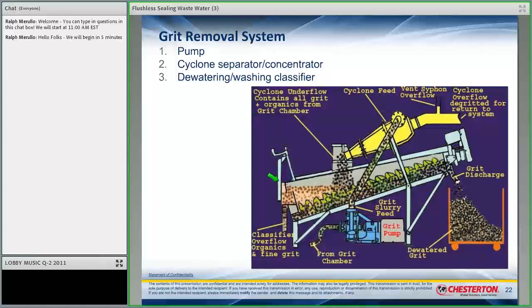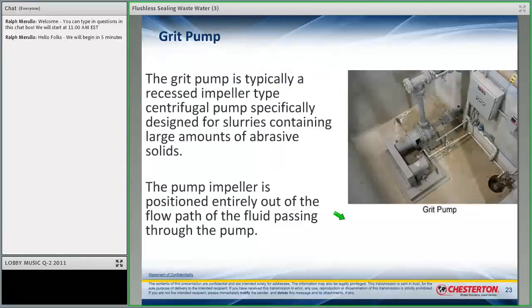So this pump generally sees what are called settling slurries, meaning the solids will settle out of the fluid. And so it's a fairly aggressive service in terms of a slurry, right? And again, you have a process here where you don't want to add more fluid, because the whole purpose of this is to separate the solids from the fluid. Absolutely. Right? So these are examples of grit pumps.